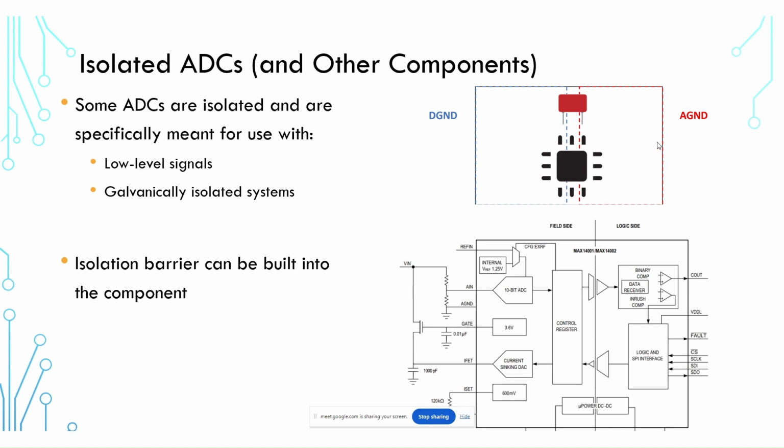So essentially what we would have here is a digital ground and an analog ground, again, galvanically isolated. Here we have a specific reason that we want to split into two separate ground regions, and that reason is safety. That's the main reason that we have galvanic isolation. And we would then bridge these two, of course, with a Y-type capacitor. If we have an issue with radiated EMI at high frequencies, we can help control that with this Y-type capacitor. And then here you see that we have our isolated ADC bridging the gap between these two sides.